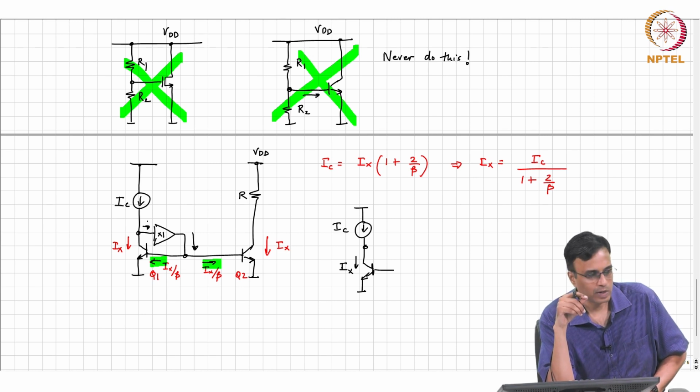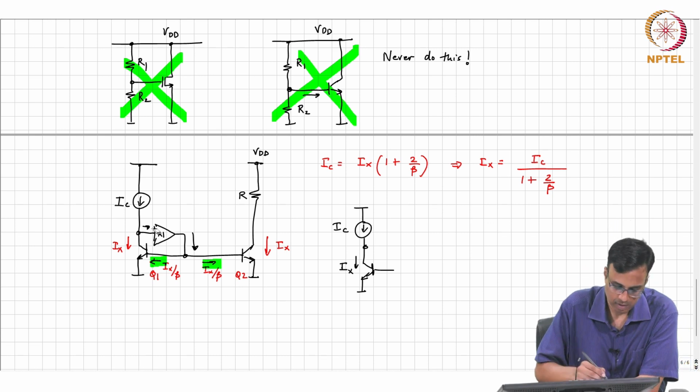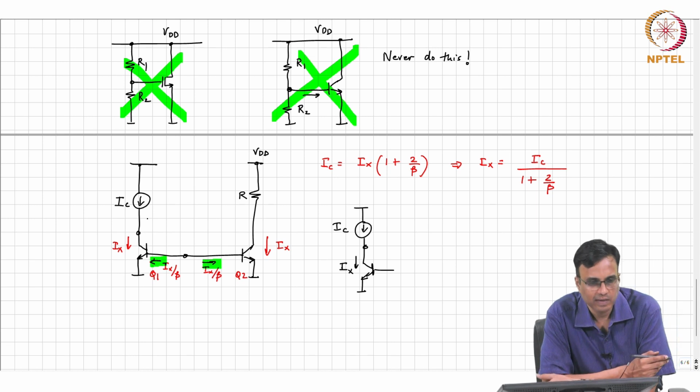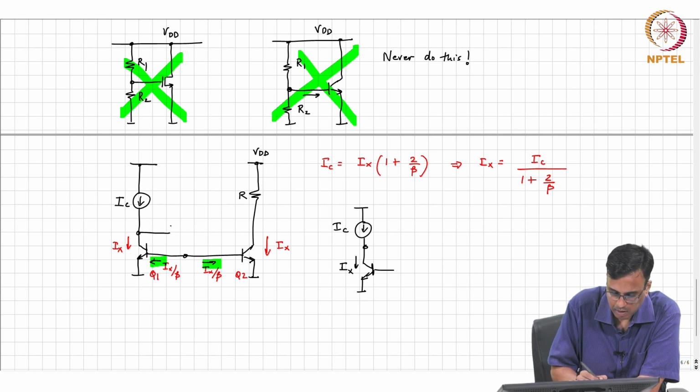Okay. Now, how do we realize the voltage controlled voltage source? How do you realize a voltage controlled voltage source with MOS transistors? What is the simplest VCVS that you know? Common drain. So, here the analog will be common collector, right.